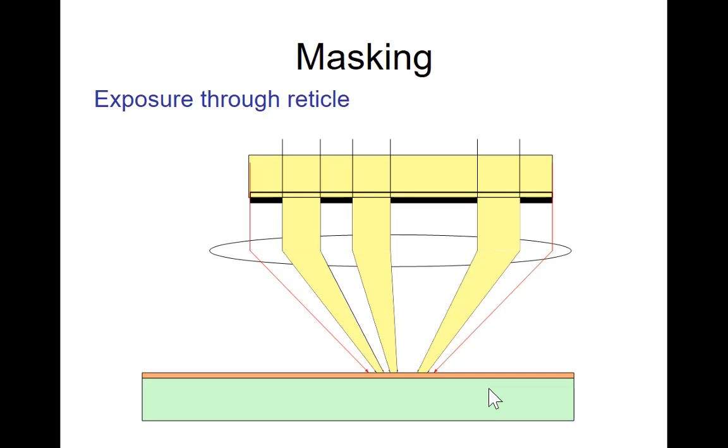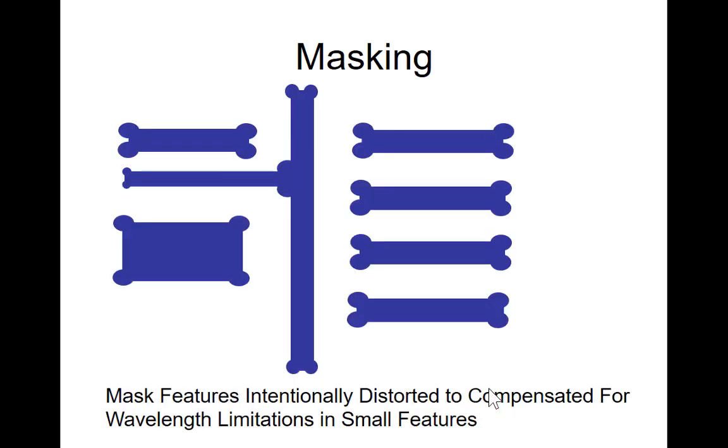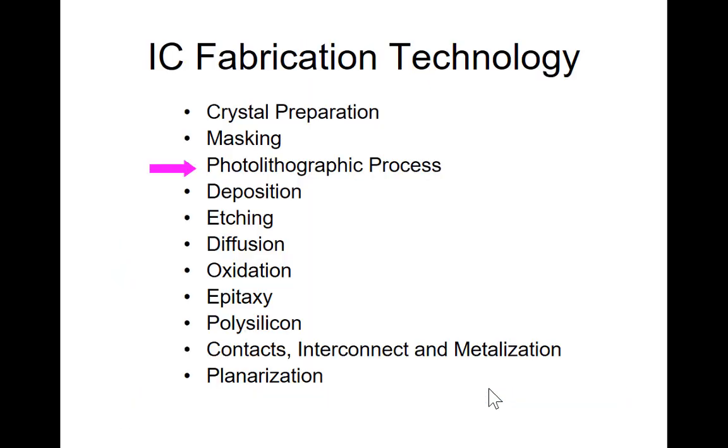We'll talk about the steps of photolithography just a little bit, and you will see how the mask is used. They can get the transfer function from the slots to the patterns, and then for the desired patterns, you do an inverse transformation to get how you should cut the slots in the masks. So now you are going to use the masks in the photolithography steps.